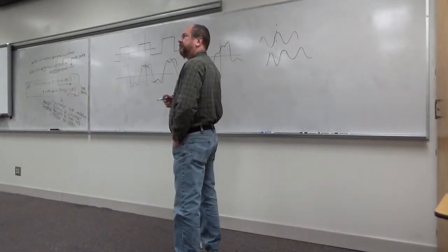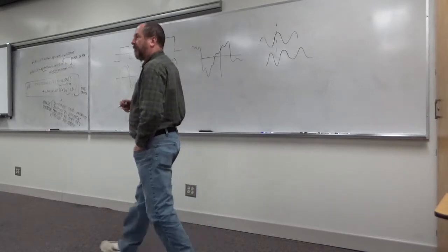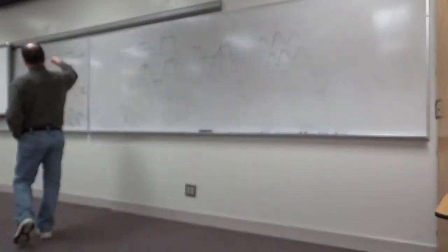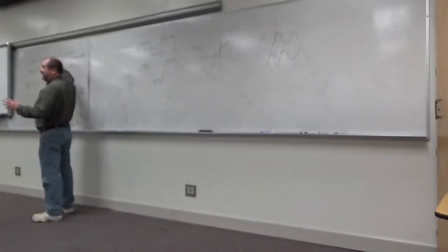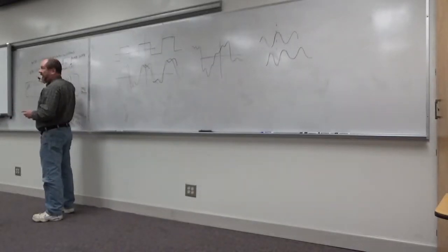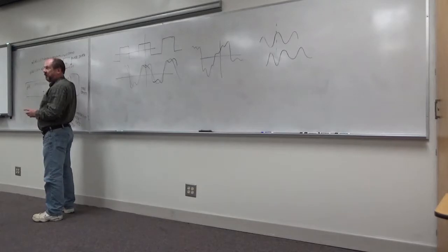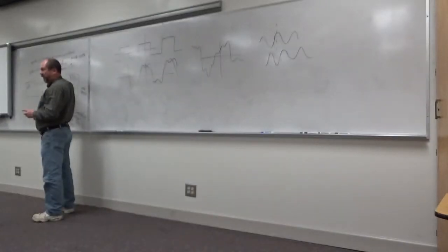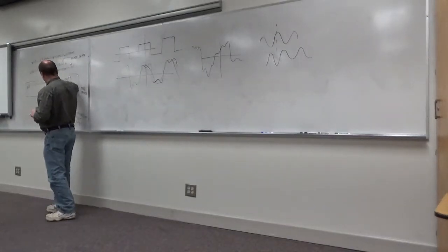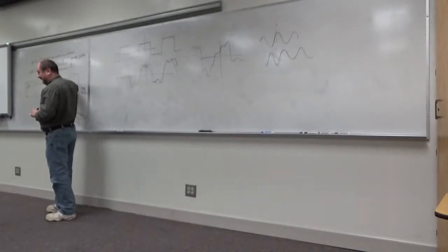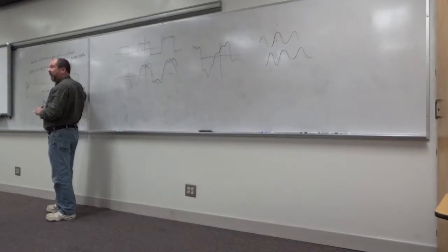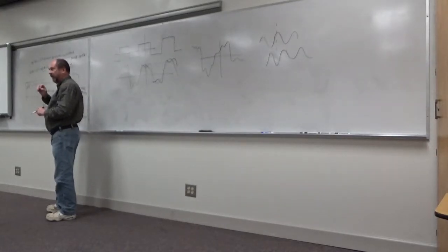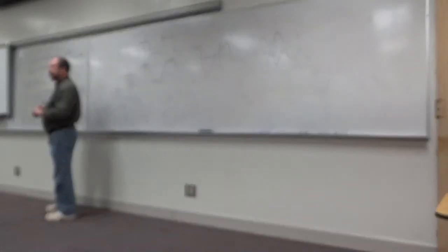So the first, the top equation with the phase shift, we don't really, it's okay. What you get there, those don't have to be equal. Those should not be equal, actually. But when you factor this out so that you get a time delay, n minus, you want all those time delays to be equal or very close to equal. And if they're not, that's when you have phase distortion.